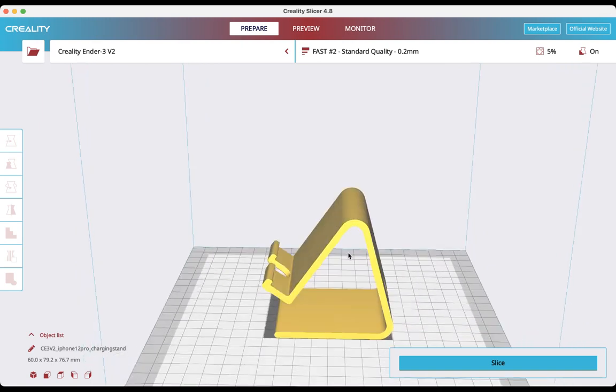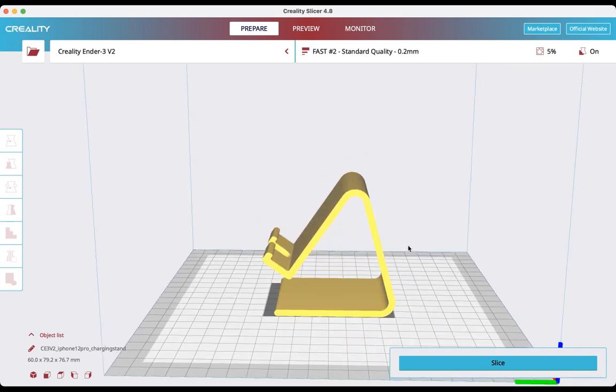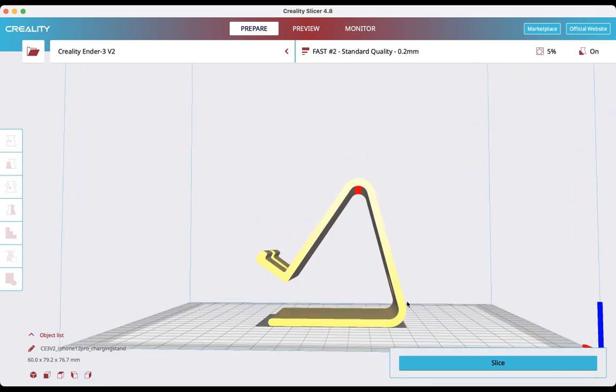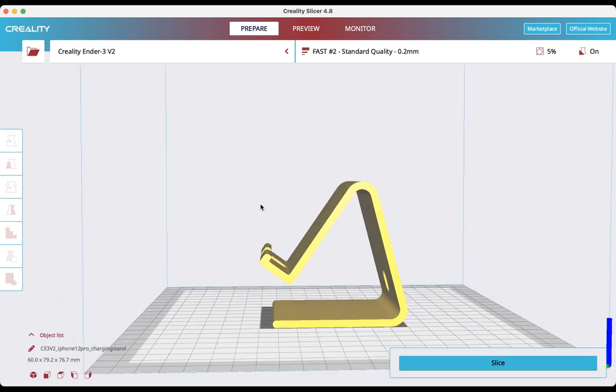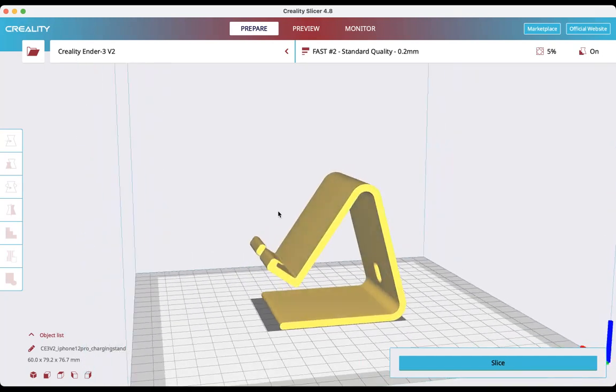So what the 3D printer will do is it'll print from the bottom, it'll gradually print up and up and up, so it'll print this, but then as it's printing around, say, maybe around here, where it's in line with that. When it gets to here, it's going to have to start printing this. Now, it can't print that in free space. Otherwise, obviously, it'll just fall over. So what it has to do is at the same time, it has to print some support structure, support material, so that it can actually build on something. Otherwise, it's just trying to print in thin air and it won't work.